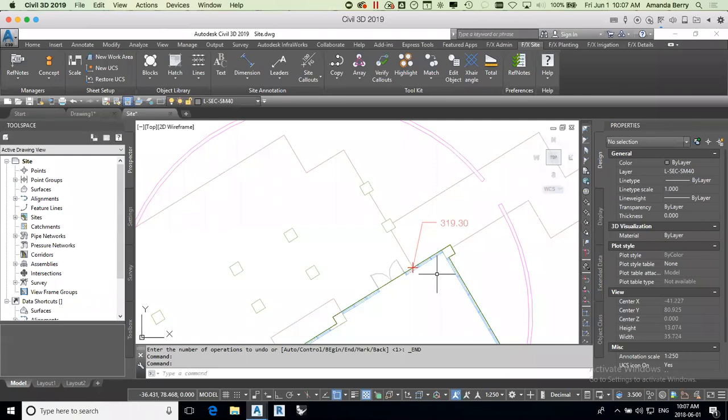I always recommend, before you go into any of these grading tools, that you have a good understanding of grading techniques, because a lot can go wrong if you just rely on the CAD tools. If you didn't draft something completely correctly, it's just going to go along with the incorrect information you're giving it. So you really do need to be able to understand and recognize when a spot elevation isn't behaving like it should, or when contours aren't behaving like they should.